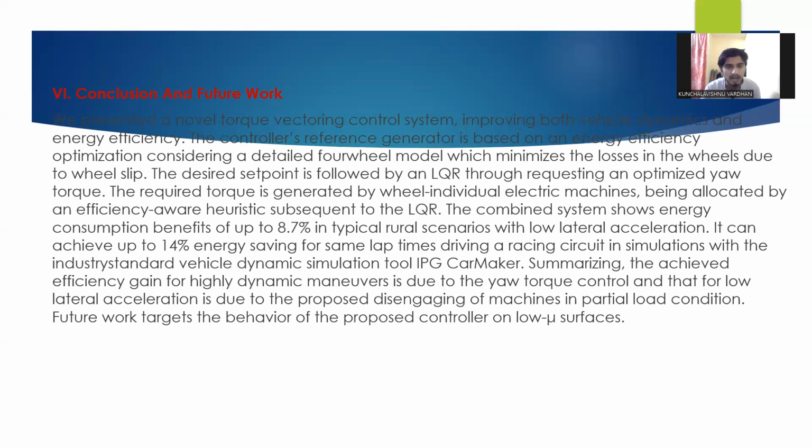At the same lap times driving a racing circuit in simulation with the industry standard vehicle dynamics simulation tool IPG CarMaker. Summarizing, the achieved efficiency gain for highly dynamic maneuvers is due to the yaw torque control, and the gain for low lateral acceleration is due to the proposed disengaging of machines in partial load conditions. Further work targets the behavior on low friction surfaces.